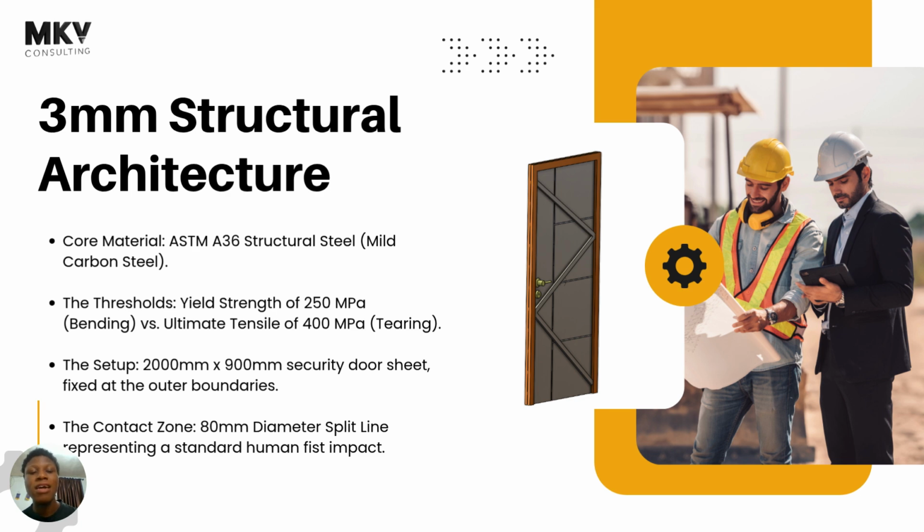For this design, I have already done the necessary. I have a 3 millimeter steel door, the frames are there and everything. I've done the geometry part, which is me modeling it, and I focused on simplicity while modeling. If you notice, we have some sort of Z reinforcement on the back.